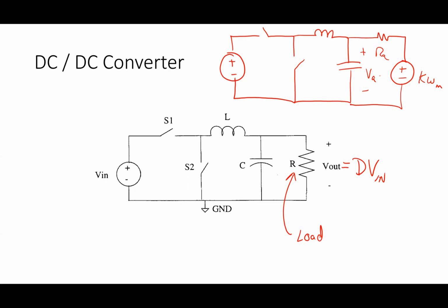Now, without me getting into the details on this, it turns out with a motor, I don't actually need an L and a C, right? I could do it by just pretty much hooking the motor up directly to the switches. And that's really what you're doing when you have that shield, right? You take that Arduino shield, and you hook it up to a motor. You don't put an LC in there.